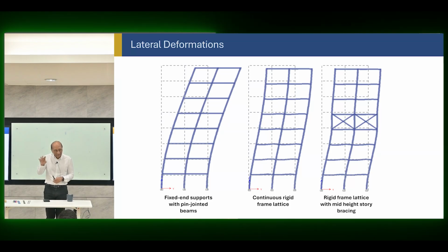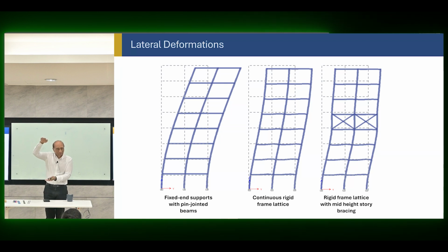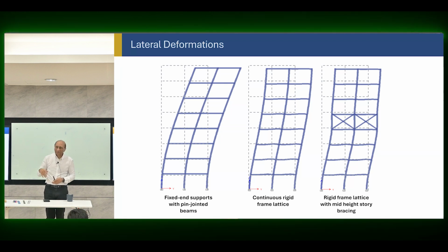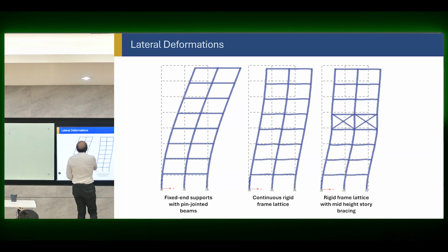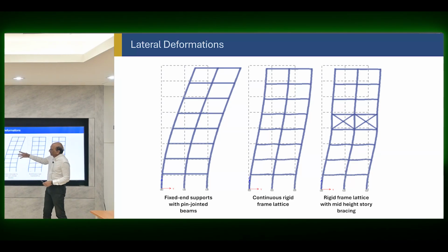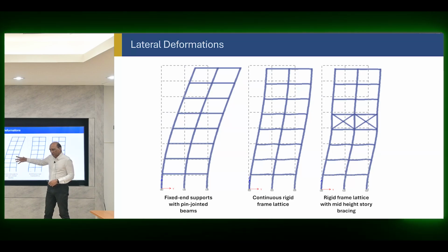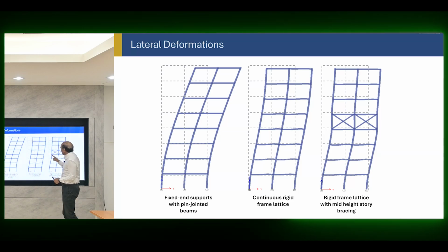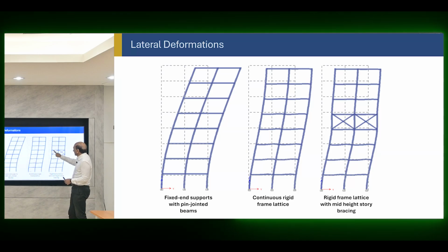And the problem with the beam is that people will not let you make it too big because, as I told you, people don't want beams anymore. There's a headroom problem. Architects don't like it. Nobody likes beams, which means that we end up with a situation where we have to develop systems which rely on columns with this system only for gravity, not for lateral, which means that we can now add a system inside.